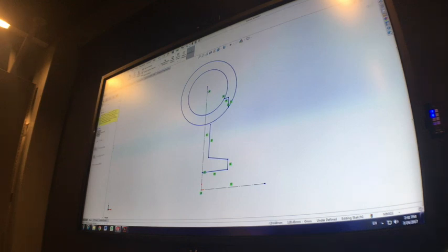And now I'm going to use powered trim. The other thing with the powered trim tool that I might not have shown you yet is that, as well as trimming lines to the nearest endpoints, you can also extend lines. So this line here, I can trim back, but if I drag it up to this point, it'll extend that line as well. So it makes it very quick to trim, extend lines and get the sketch profile that you need.